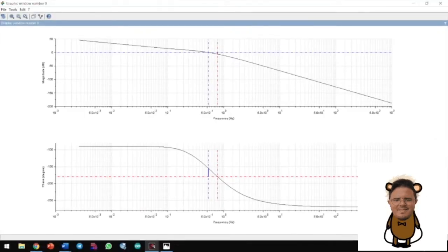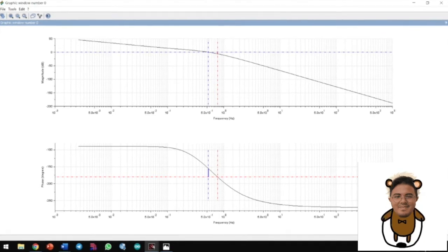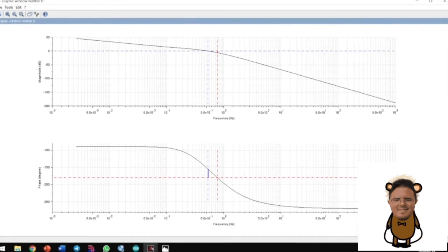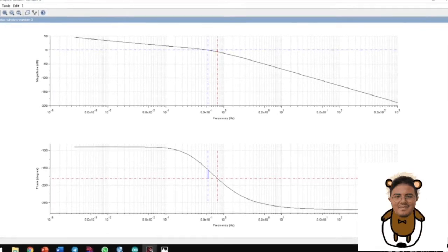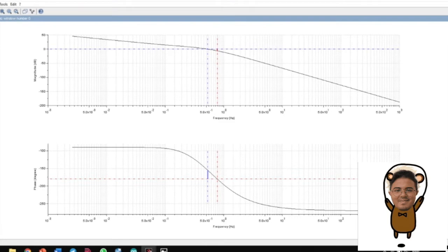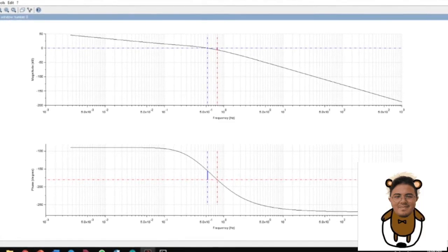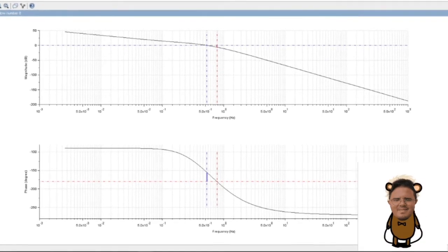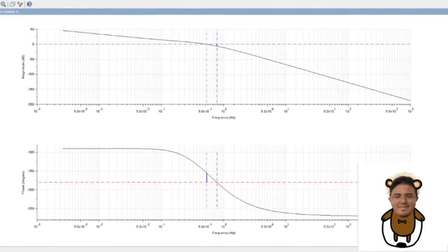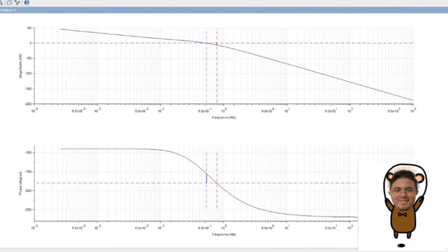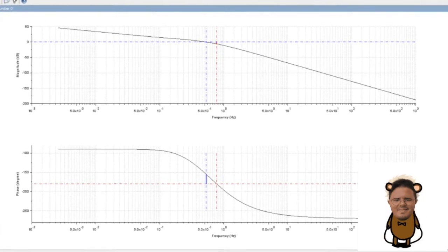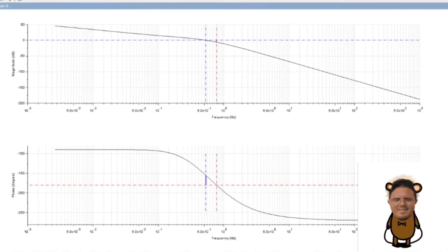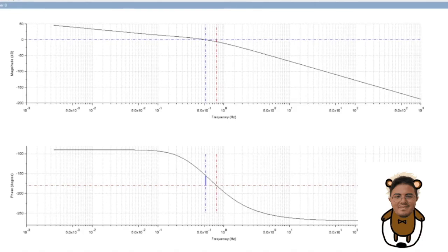From here we can see the gain margin and the phase crossover frequency from the red line, which represents 0.769384 for the phase crossover frequency and the gain margin of 6.0938238. The next one is the phase margin and the gain crossover frequency from the blue line, which is 0.5274735 for the gain crossover frequency and the phase margin of 25.032056. So that is all for my part.